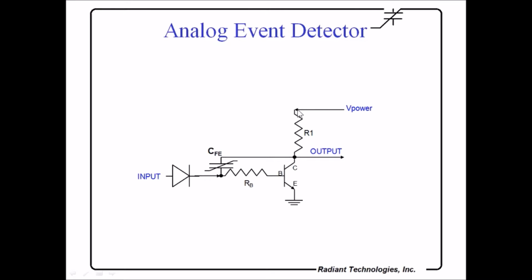So if we apply a voltage through R1 and went directly to ground here, this RC would act exactly the way we just described, or I just plotted on the previous pages. However, in this case, there is no connection to ground. This diode here prevents the charge from going out of the circuit that way, so it all must go through the base resistor of an NPN transistor to ground. So my R now, these two resistors combined, here's my C.